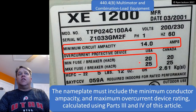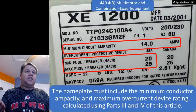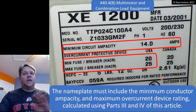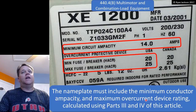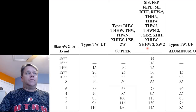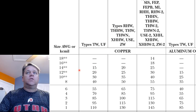It has to be at least 20 amps, but it can't be more than 25 because we have to provide protection. We're going to use a 25 amp breaker. All right, that's not subject to debate. That's what we're doing. We're using a 25 amp breaker. I don't have any 20 amp breakers in the truck. We're using a 25. I need a wire that can carry 14 amps. 15 amps, 14 gauge. Beautiful.